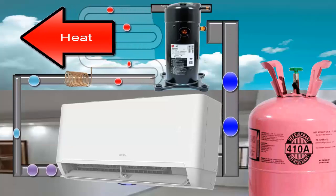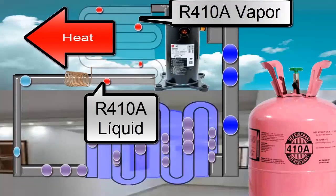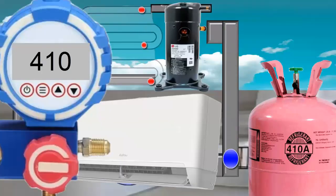The gas pressure after the compressor, in the condenser unit, generally exceeds 400 pounds per square inch, psi, and must be measured with the red pressure gauge. The R410A exits the condenser unit in a liquid state but with high pressure.